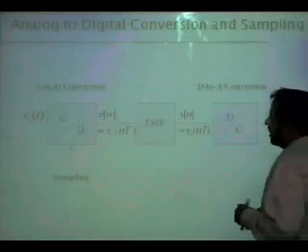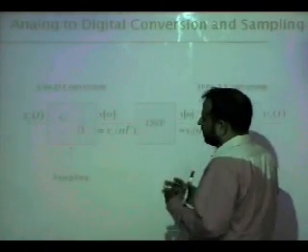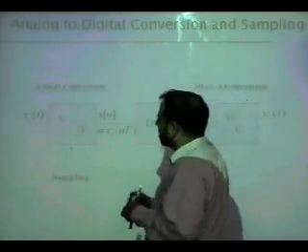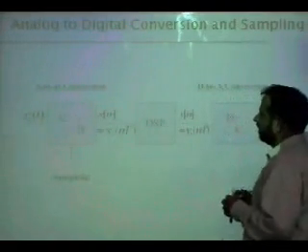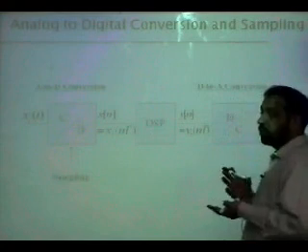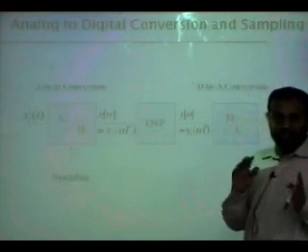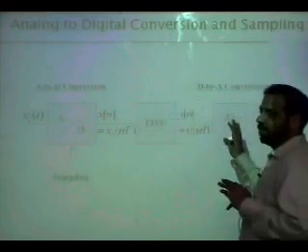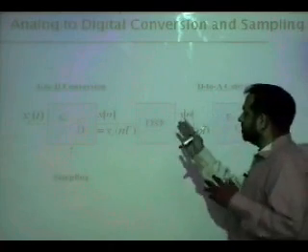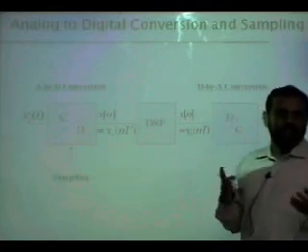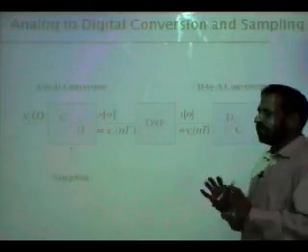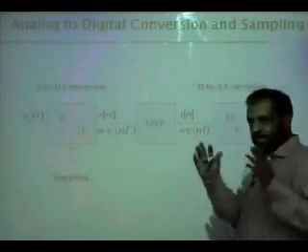In this, sampling means, from the chapter's perspective, a continuous to discrete time converter. It says while learning sampling, let's not really worry about quantization, though quantization has a big effect on the overall system. Quantization means how many bits you get once you sample a signal. So the number of bits per sample is important. But this book starts with saying ignore that.